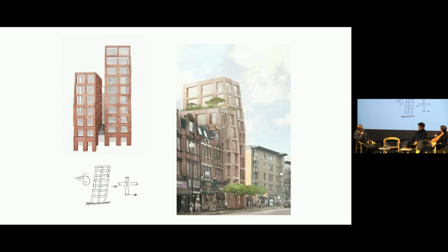So here we're using the stone, unreinforced pieces of granite and basalt, to form a moment frame that's 10 stories high. When the wind blows, it's the unreinforced stone that stops the building from falling over in the wind. So initially I was thinking, Jesus, do we really want to do that? We're going to have unreinforced basalt, a 10-story building in the wind, and it was quite arresting.